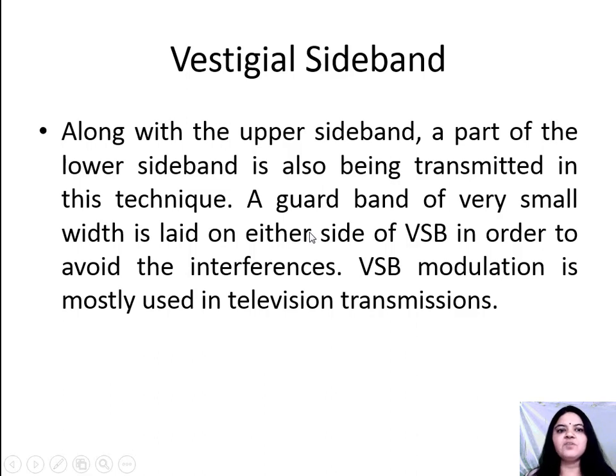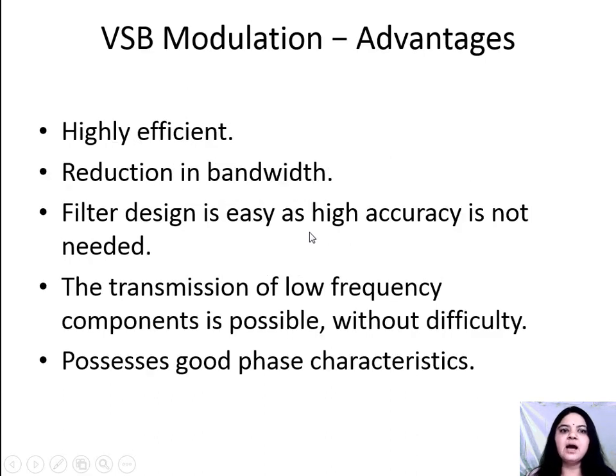The advantages of VSB modulation are: it is highly efficient, there is a reduction in bandwidth, filter design is easy as high accuracy is not needed, transmission of low frequency components is possible without difficulty, and it possesses good phase characteristics.